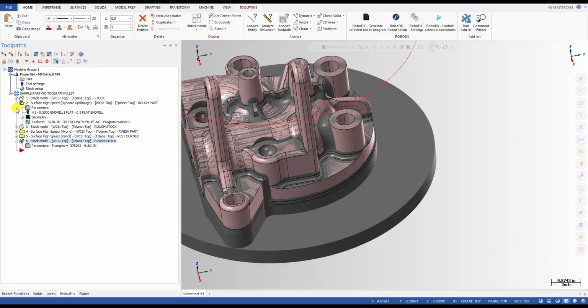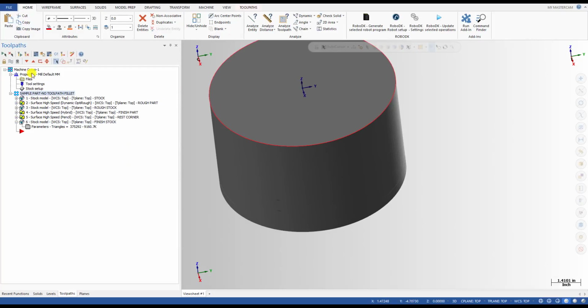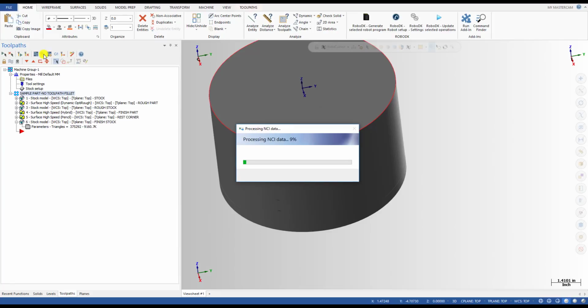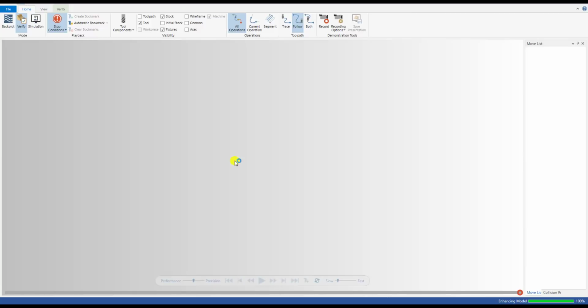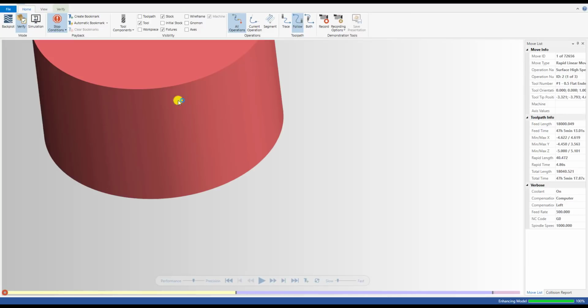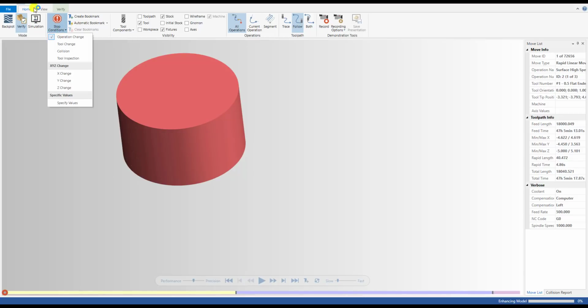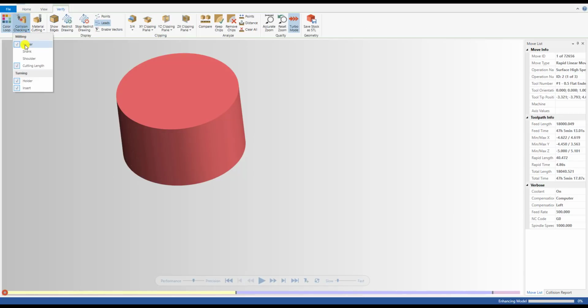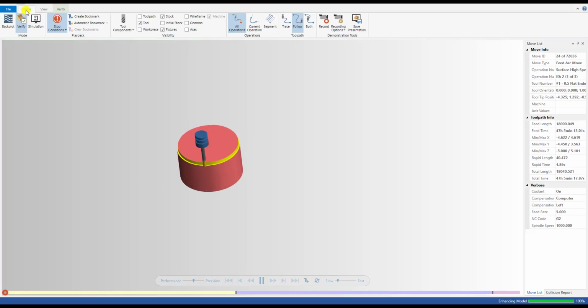So this is the time for the Toolpath fillet. First we try to simulate it. Because this part has some collision, I'm going to turn off the collision checking just for demonstration only. And this is the roughing Toolpath. I will make it fast.